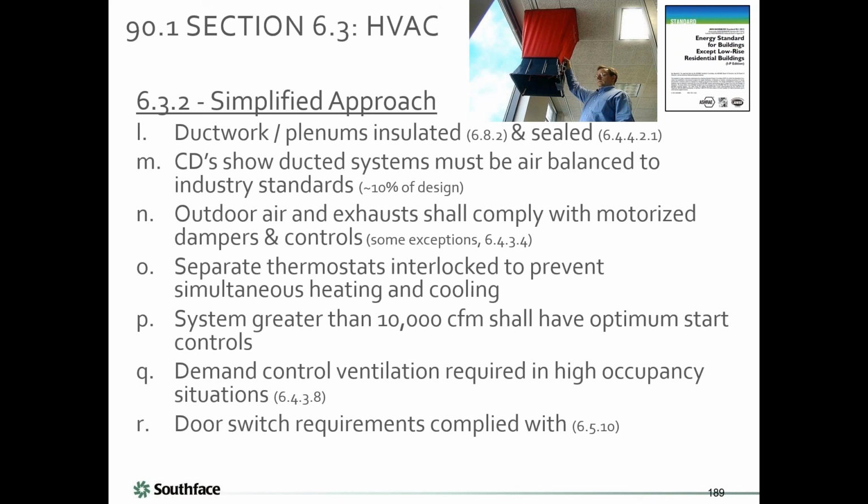When the CO2 levels drop, or people leave the room, the damper can start to throttle back down. So it's kind of like an occupancy sensor for a space, but it's controlling how much fresh air. It really makes sense. It really saves energy. Probably the new thing is that they just want you to use it in more spaces. So it's sort of more applied, but it's already in our code.